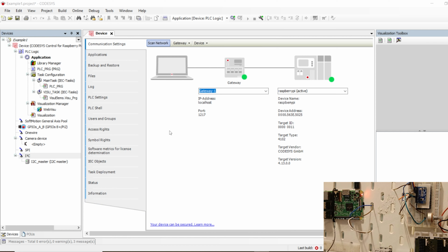Now, one thing to note about I2C in Codesys here is, unlike protocols, for example Modbus, which defines the server data buffers and the functions to read and write data to those buffers, which we call registers, I2C is kind of different. Each device vendor will define their own data buffers and the mechanism of how to access data and read data from those buffers and write data to those buffers.